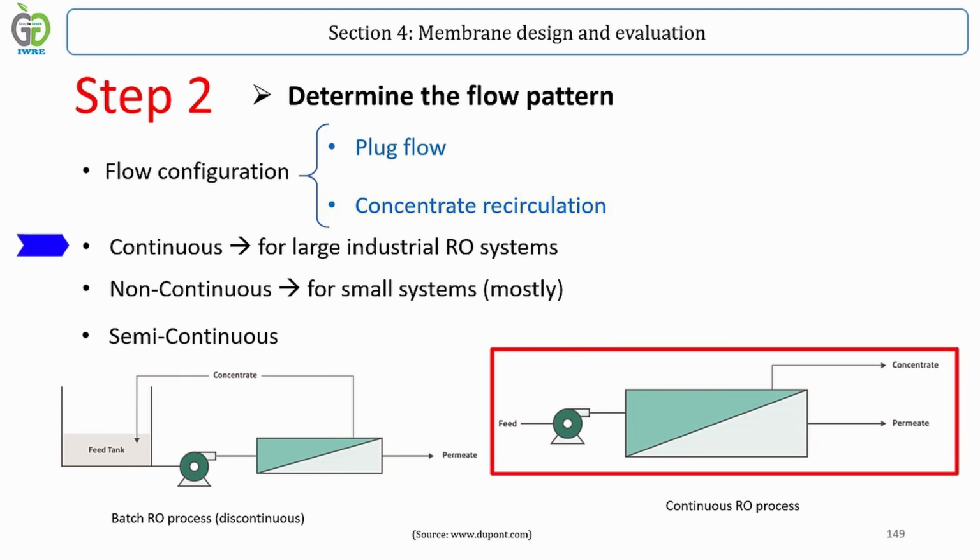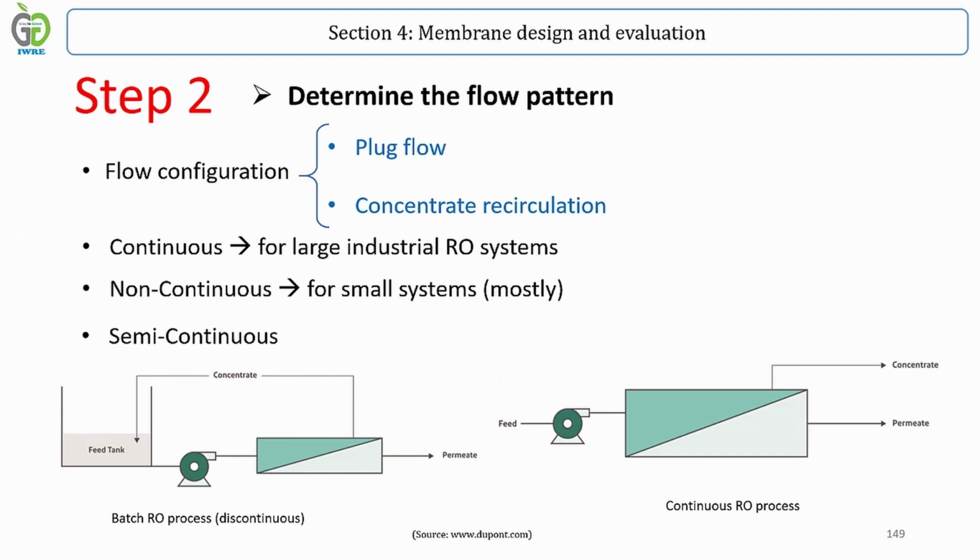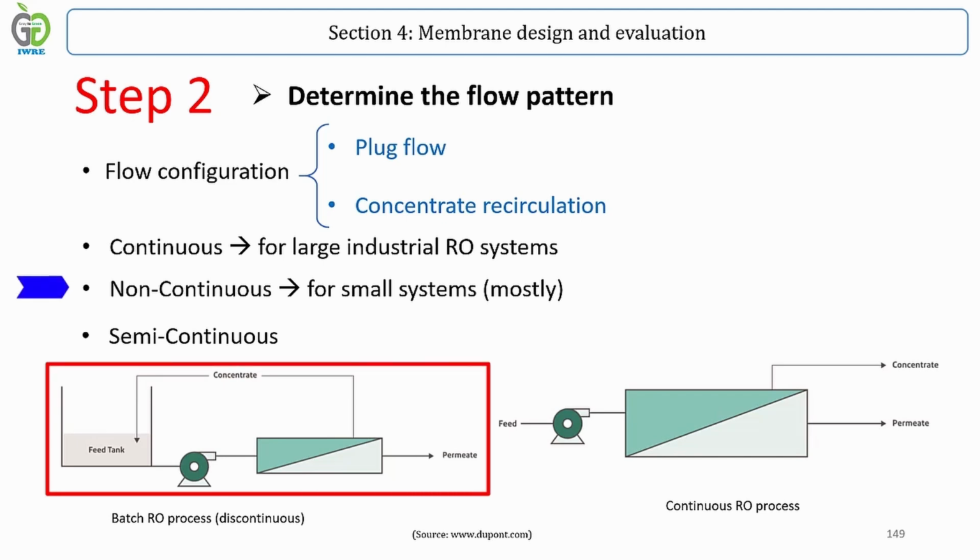A reverse osmosis or nanofiltration system is usually designed for continuous operation, in which the operating conditions of every membrane element in the plant are constant with time, as illustrated in this figure. In certain applications, when relatively small volumes of special feed waters occur discontinuously, such as wastewater or industrial process solutions, the batch operation mode is preferred.